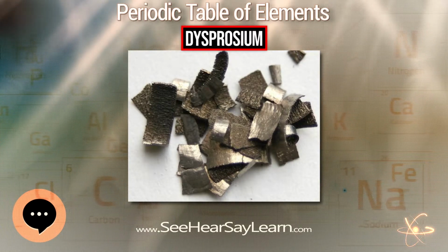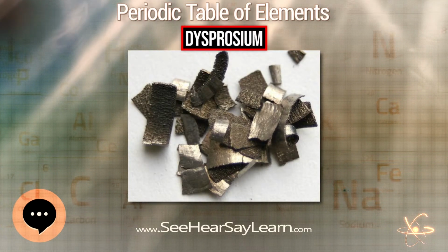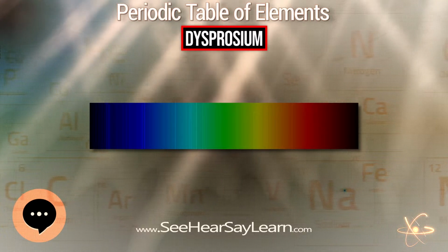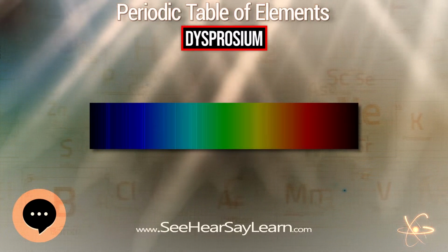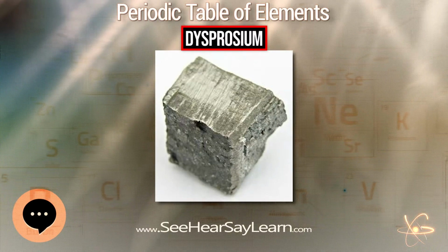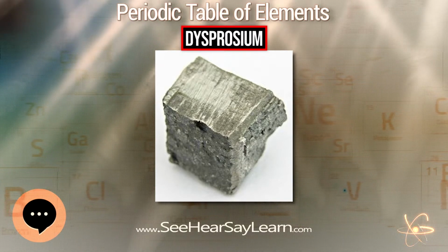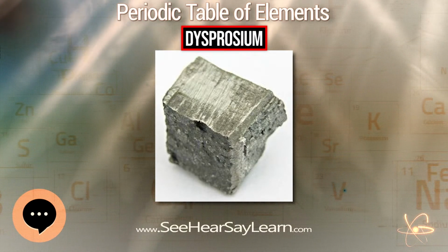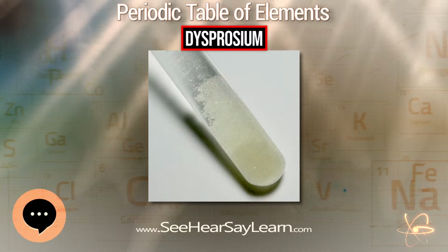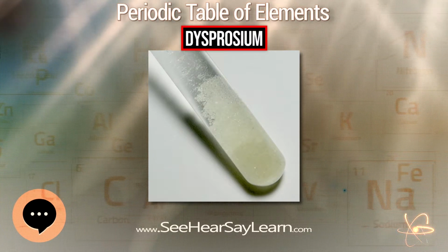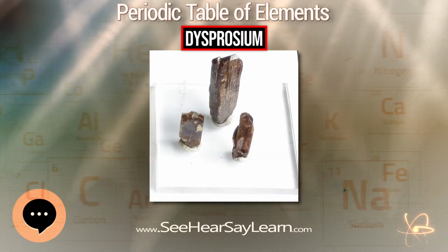The dysprosium substitution may also be useful in other applications because it improves the corrosion resistance of the magnets. Dysprosium is one of the components of Terfenol-D, along with iron and terbium. Terfenol-D has the highest room temperature magnetostriction of any known material, which is employed in transducers, wideband mechanical resonators, and high-precision liquid fuel injectors.